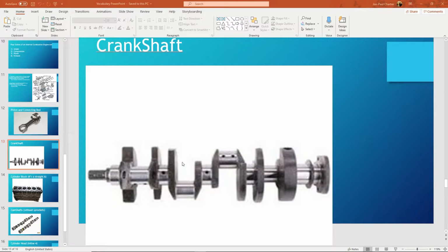They're all different, and the reason is this is a 4-cylinder, 1, 2, 3, 4, and I do not want all 4 cylinders doing the same thing at the same time, right? So this one is 180 from that one, this one is 180 from that one, and the firing order on this one might be something like 3, 4, 2, 1, or however. But you'll notice that we do that on purpose.